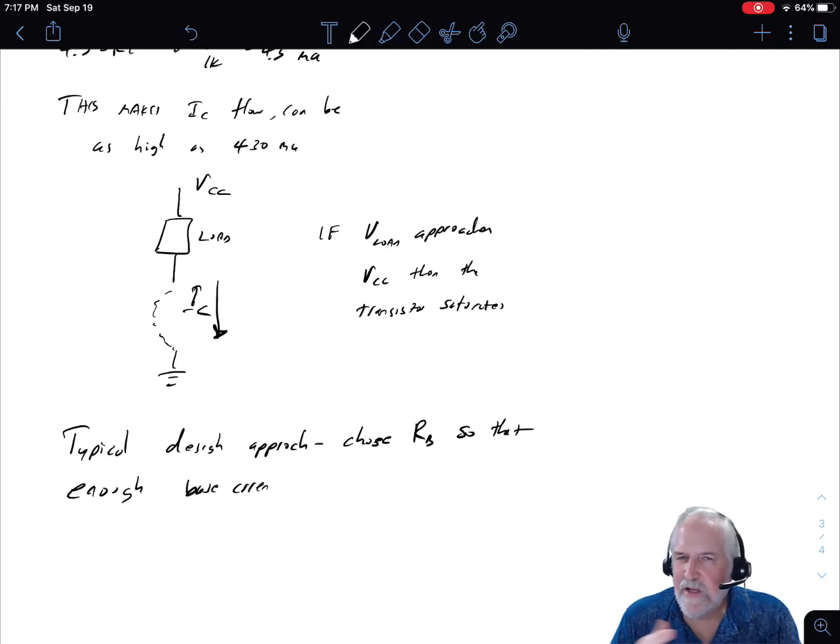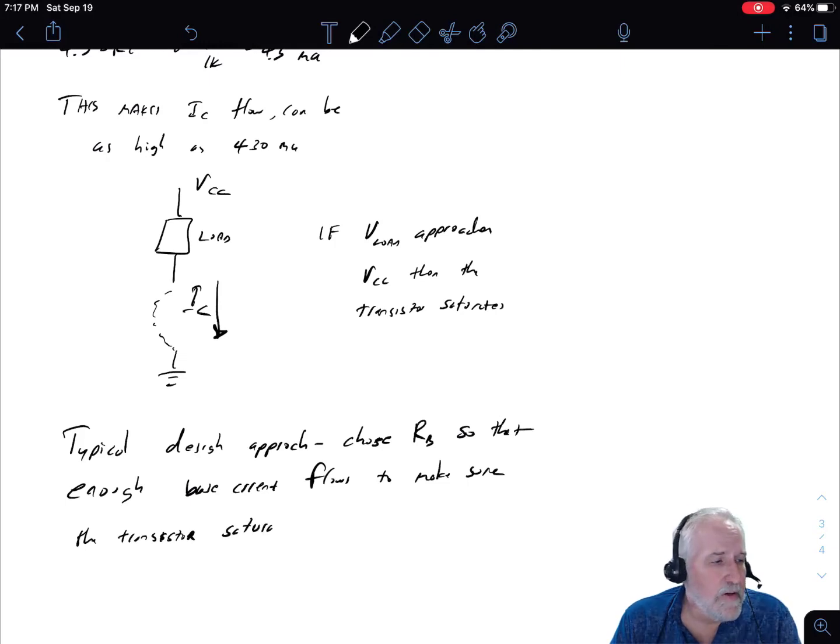You have to understand that base to emitter junction. You've got to worry about how much current's flowing through there. You want to make sure there's not too much current. And I'm setting you up, because there are some BJTs in the kit, right? Some of the smaller ones that look like the thermal sensor we were looking at in the Arduino startup kit.